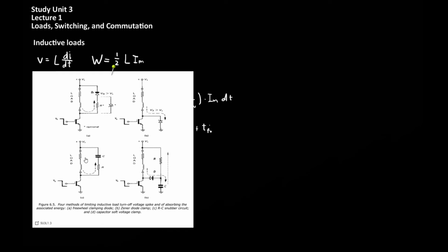This circuit over here is an RC snubber network. The idea behind this circuit is that the RC snubber will leak energy away from the inductor when the voltage gets too high. This circuit here effectively creates a resonant network which will drain any excess energy away through the resistor and capacitor and back into the source. More technically, this RC network forms a filter which will have an overdamped response, which will dampen any voltage spikes which develop across the inductor.